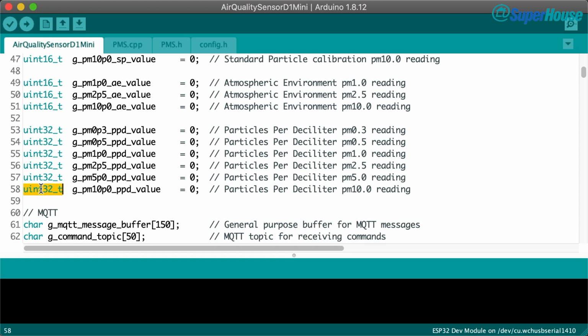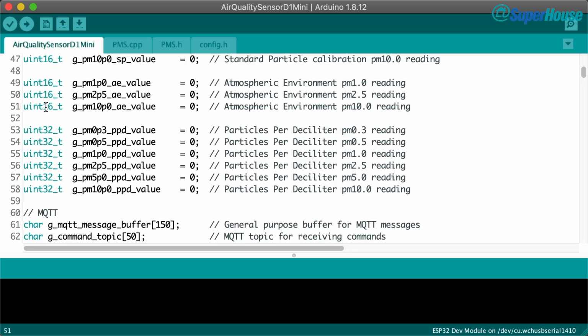You'll also see that I've declared these variables using things like uint32_t and uint16_t, and I haven't used int or long, the sort of typical aliases that you find in Arduino programs. That's because those aren't really very specific. They depend on the architecture. If you declare a variable as an int, is it 8 bits long, 16 bits long, 32 bits long? Like, who knows? Sometimes it's one, sometimes it's another. It depends on the target platform. So you can write code that will compile differently onto different targets in unpredictable ways. So if you want a 32-bit unsigned integer, then declare it as a 32-bit unsigned integer. Don't just use long and hope that that keyword is correct in the particular environment that you're compiling on.